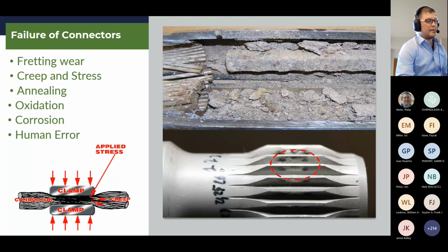So when you have a line and a long span, you always worry about sags and the sag charts. If you run at a higher temperature, the sag is going to increase. Now, if you heat it up past a certain point, then that sag is not going to go back to its normal state. That's what you can see starting to happen in this situation. And then ultimately, it makes the metal more ductile.